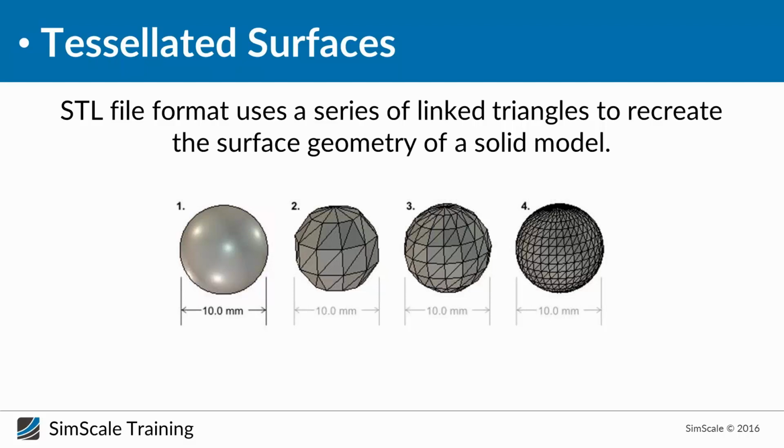For example, with a front wing or any wing, in the leading edge you have to increase the tessellation because you have the curvature. Otherwise, you will have a really weird shape that will not represent the real geometry that you want. So we have to increase the tessellation.